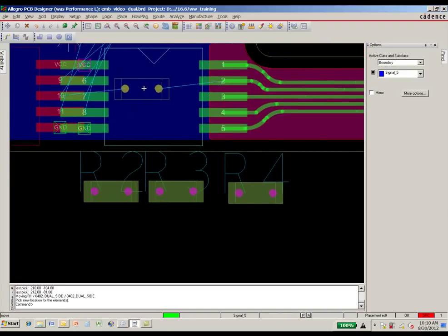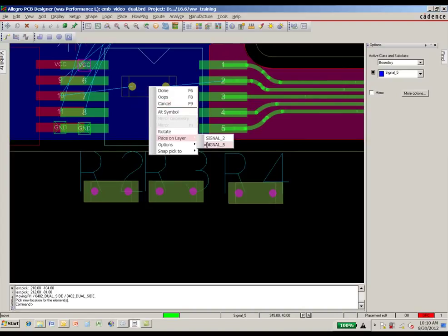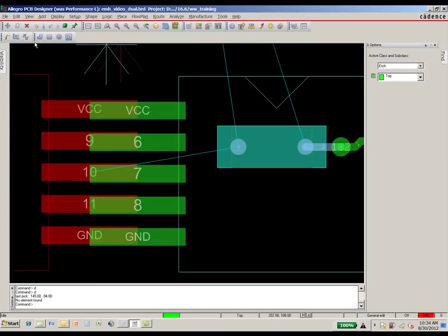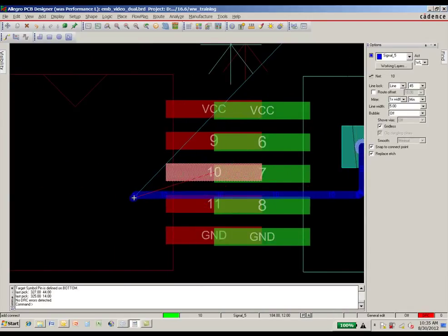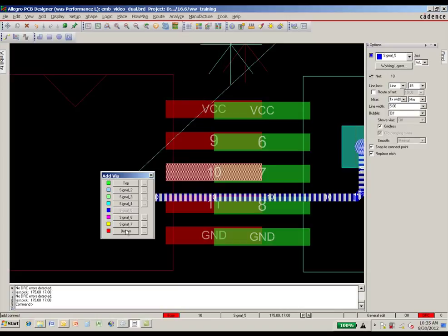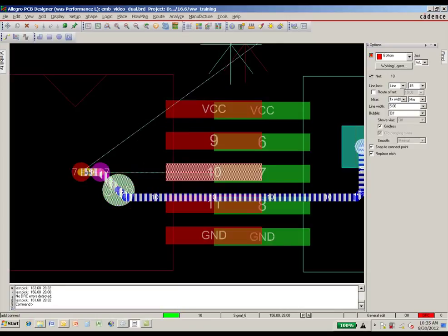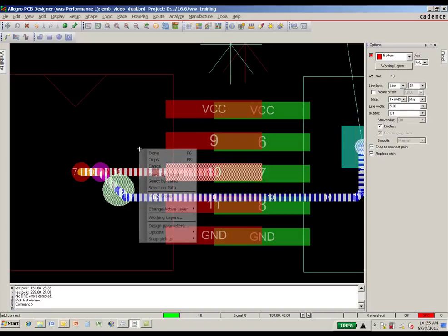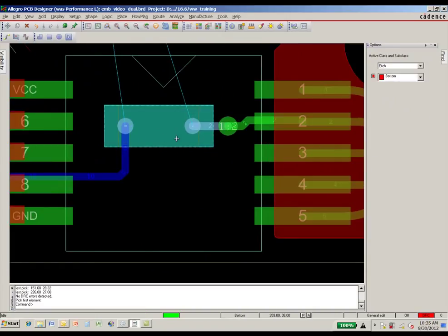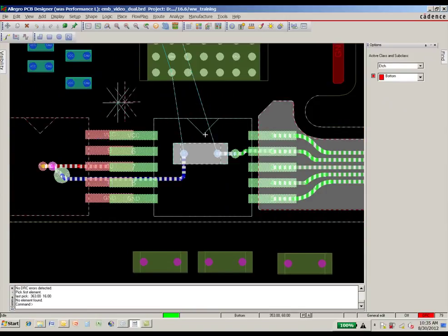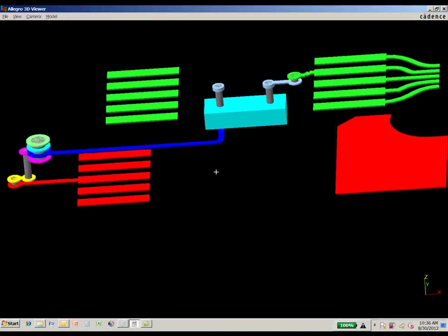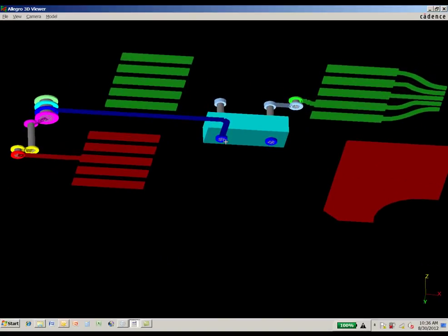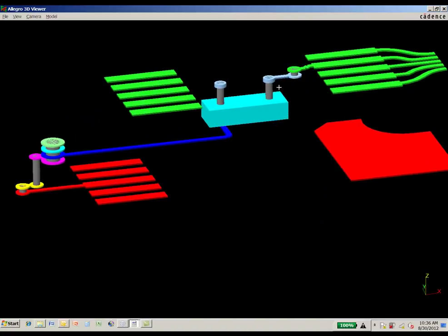I'm going to now move one of these components and drop it on internal layer 5. I'll use the routing tools now to show we can route from either side of that dual side contact component. I'll begin on layer 5, the base of the component, and use the working layer model to add a series of micro vias that get me to the bottom layer. The right side of that component has been routed off of the top layers. Next, I'll highlight the circuit and go into a 3D mode and spin the graphics a bit to see the view of the dual-sided contact and its routes.